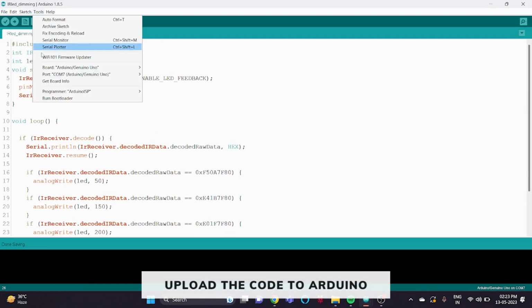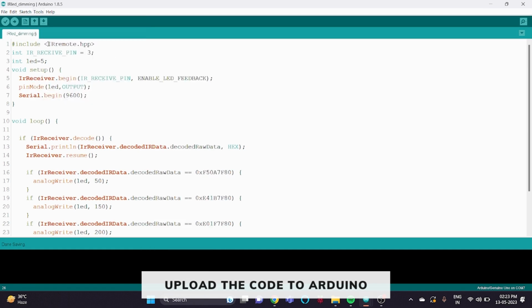Now click on Tools, select the board as Arduino Uno and the port as COM7, and then click on Upload. Your code will be uploaded to the Arduino.